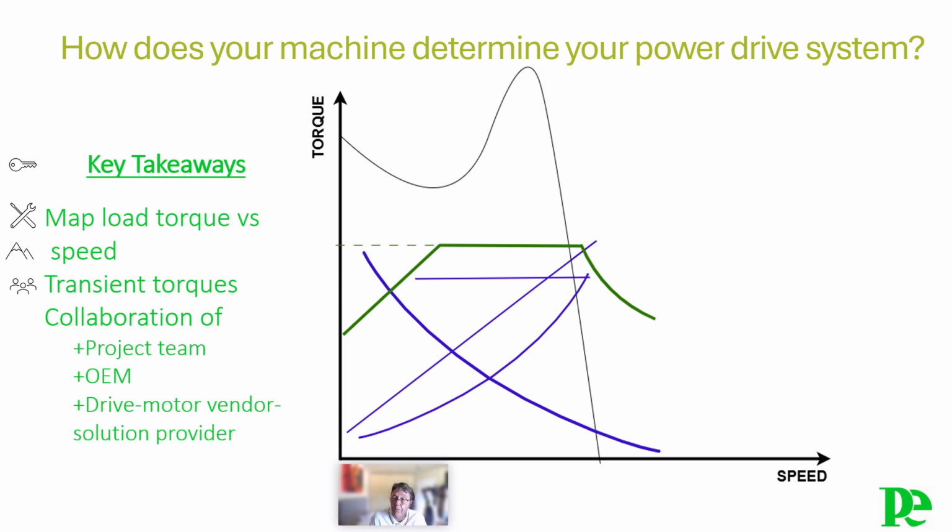Another example is a rubber mixer with regular substantial torque surges because of the operation in batch mode. New batches can impose up to 250% of rated torque. It is clear proper sizing of the motor and the drive needs to be considered. Further investigation of the machine's expected dynamic behavior related to torsional analysis and resonance speeds may be required in some cases. And last but not least, the close collaboration of your project team with your machine manufacturer is preeminent.